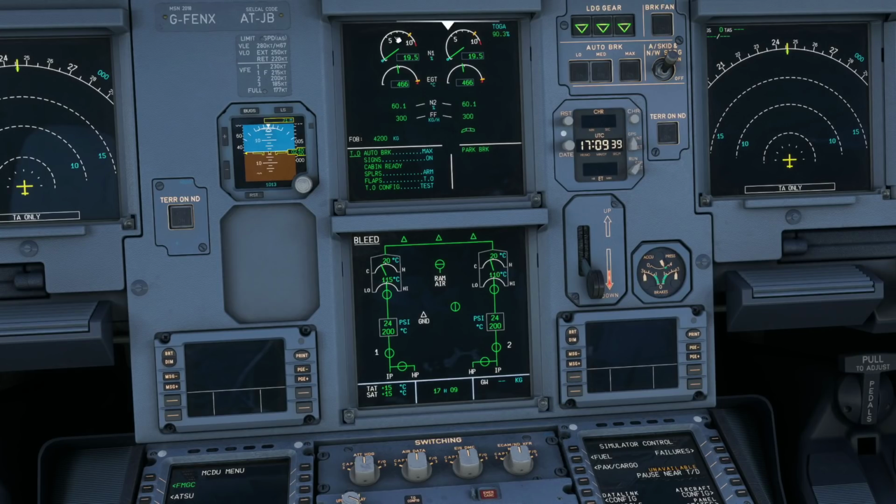So if we increase the thrust, you're looking at these two readouts right here. So up comes the thrust, and we've just sent it straight up. So it goes up to about 210. So you can see the HP valve has disconnected, doesn't need it anymore, but it's come up to 210, and now the valve is, again, opening, and it's regulating itself back down to 200. So the valve is not a yes or no, it's not a bool, it can open as much or as little as it needs to. So it's not just open or close.